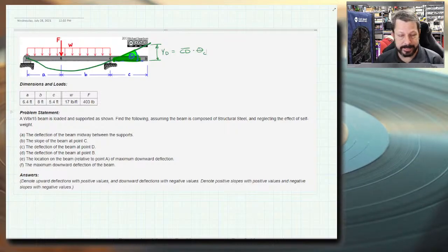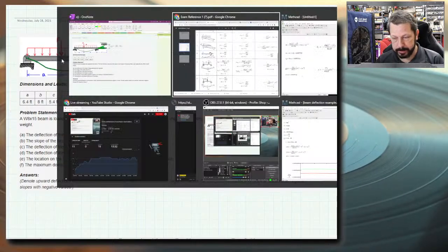So I need the distance from the support to the point load, but on the longer side, so BC instead of AB. So the eccentric point loads are really tricky to deal with. I'm going to put in what I have labeled as B as the value for X once we get to that.